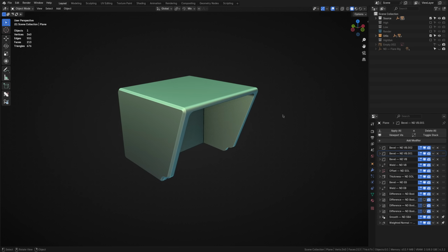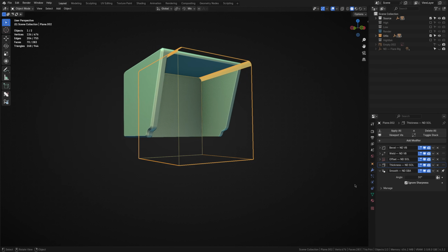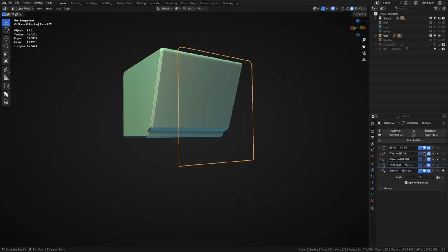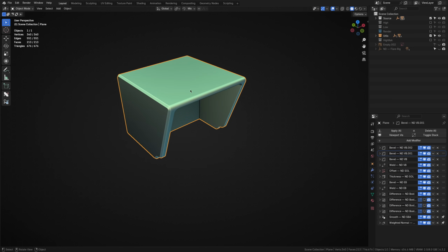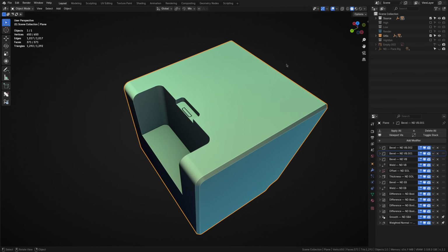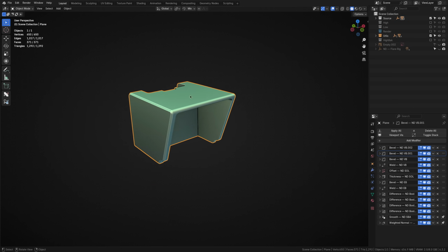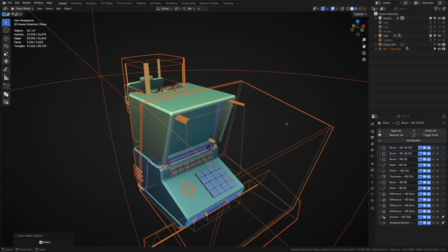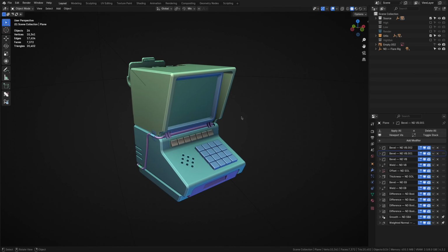Let's examine the cutting utility. It was created non-destructively using a plane, some vertex bevels, and an extrusion. I then took a similar approach at the back with a few sequential cuts. And there you have it, another detail modeled non-destructively by applying the principles we've learnt to a reference image. If you continued this process for the rest of the model, you'd have a completely non-destructive version of the reference.